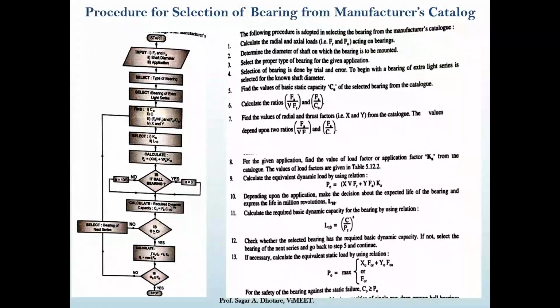Finally, we need to check that the value of C0 should be greater than the value of P. So the static capacity should be greater than the equivalent dynamic load.